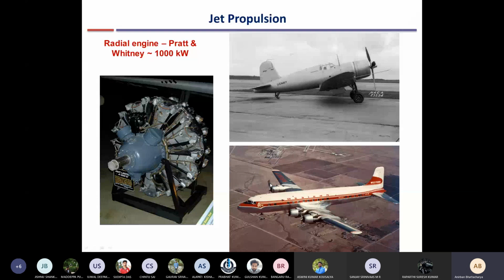And you can see that this is a very old aircraft because the windows are square windows. Okay, and you might know why nowadays there are circular windows: there was an accident and it was found that the crack propagation started from the corner of the square window because of stress concentration, and as a result all modern aircraft, for the last many years, have rounded windows, not square windows, so that there is no stress concentration.